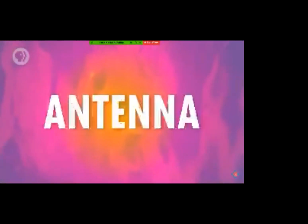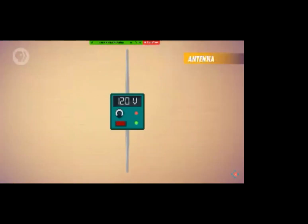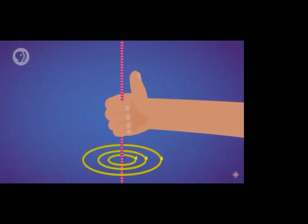To prove it, let's look at an object that can produce electromagnetic waves and transmit them through the air. An antenna. This antenna is made up of two conductive rods, each attached to opposite ends of an AC generator. When the antenna is operating, the two rods switch between being positively charged and negatively charged as the generator changes voltage. And when one rod is positively charged, the other is negatively charged, and vice versa. When electric current travels up into the top of the rod, you can use the right-hand rule, pointing your right thumb in the direction of the current, to see how the magnetic field flows around the antenna.